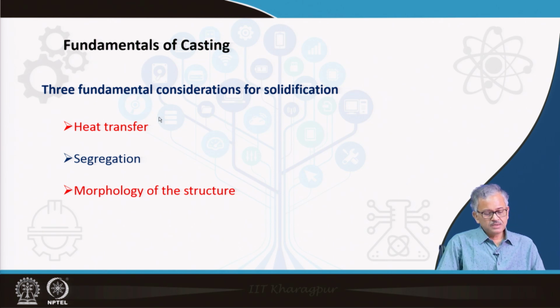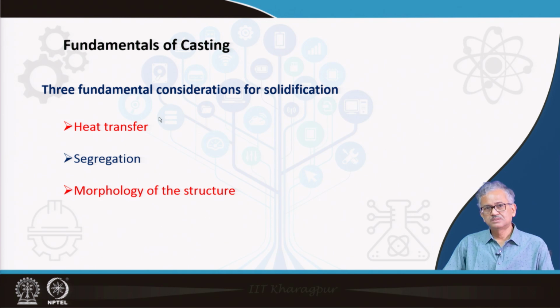And then another important thing during solidification is the morphology of the structure. There is the morphology development during solidification, that is, what type of morphology it is: planar, columnar dendritic, or equiaxed dendritic. So, how this transition takes place and what the parameters responsible are, we will also discuss.